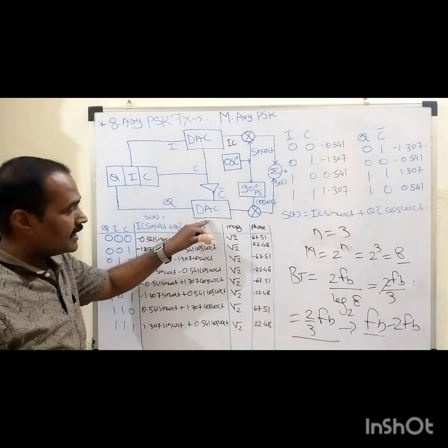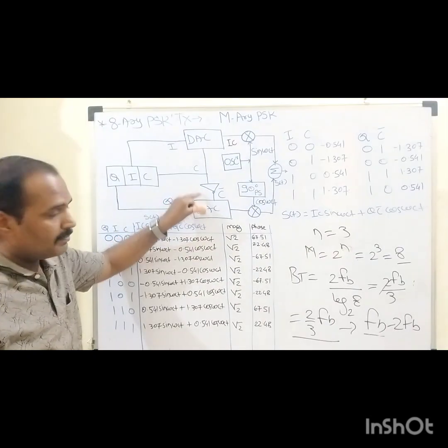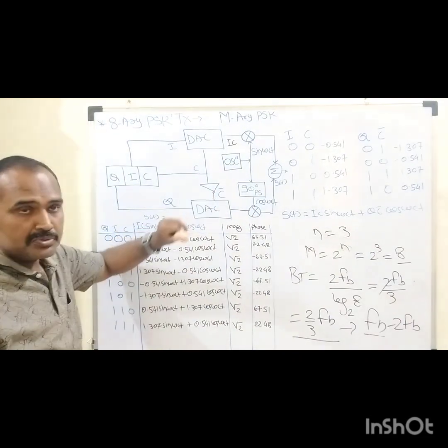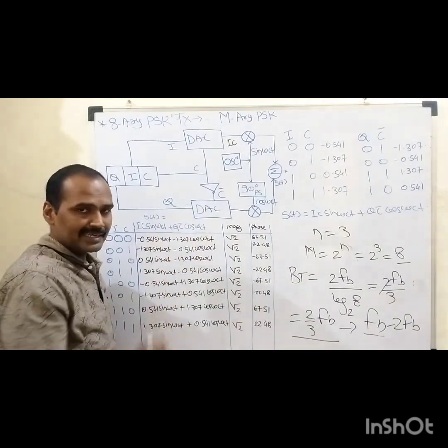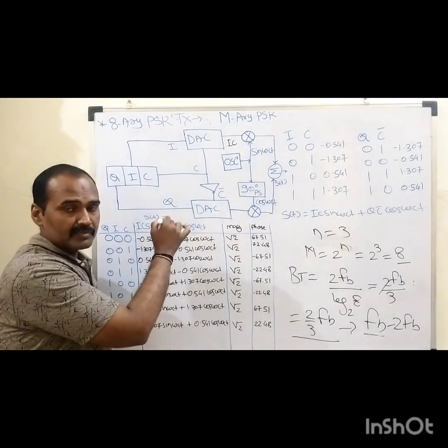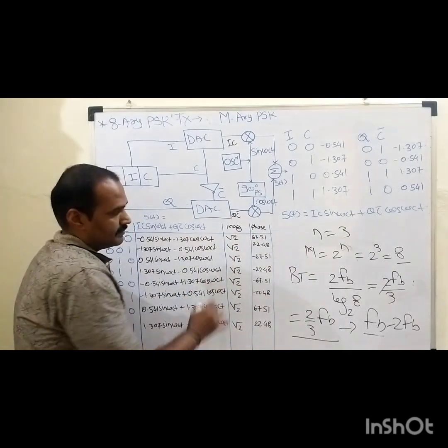As far as the lower channel is concerned, one identical inverter is connected to the upper terminal of this lower channel, so this C is inverted into C bar. So what kind of multiplied symbol sequence is generated by the lower digital to analog converter? By accepting the Q bit, it will generate the desired Q into C bar, right?